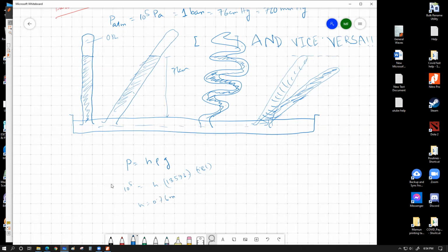Now, even if I don't use these numbers, let me just try to give you a bit of an idea how the rho actually helps us. If I subject the h from this equation, have a look. h equals, what will come? Pressure divided by rho into g. If you try to understand, pressure of the atmosphere is a constant. g of the Earth at a specific point on the Earth's surface is also a constant. So h would be practically dependent upon this density.